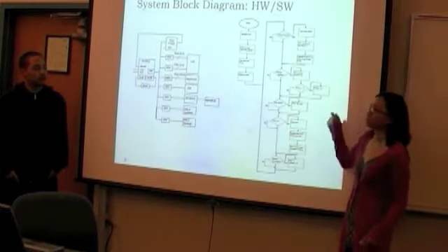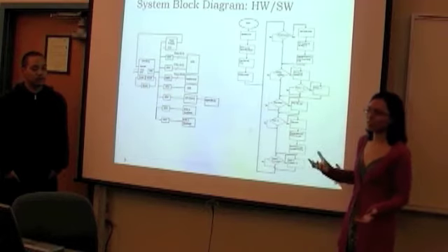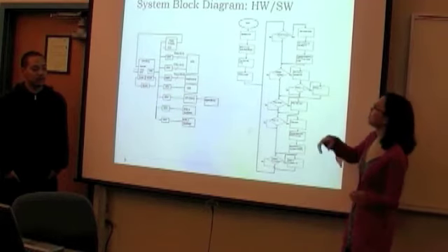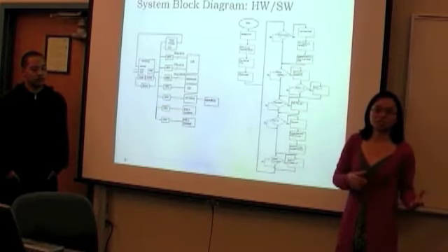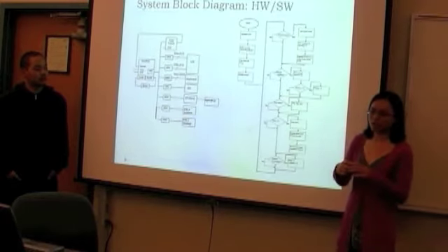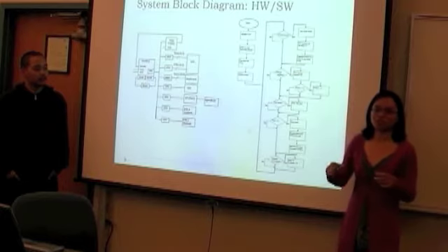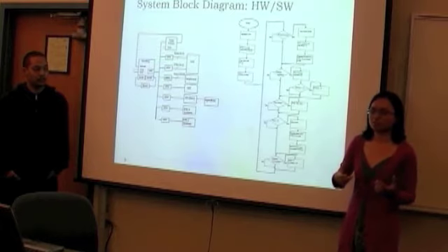So first we check if a key has been pressed on the keyboard. Then it says, okay, if none has been pressed, it's just going to go to the next step. But if a key has been pressed, it gets a scan code, and we set a flag, so it says, okay, later on in the code, it will actually play the note. And from the scan code, we get the position in an array with the set of frequencies in it. And it says, okay, it'll be that spot in the array to get the frequency for the note.